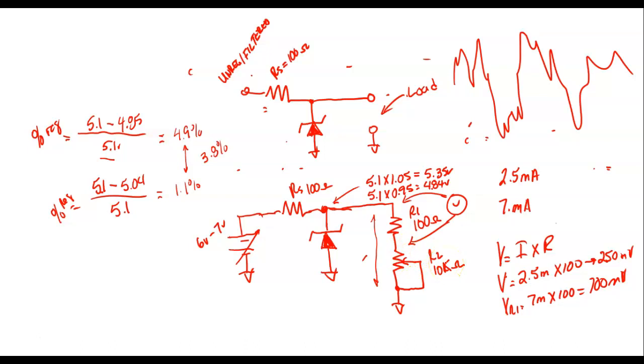So what we did here is we used the voltage changer to change the input voltage, and we went over to the side and used the rheostat to change the R2 current and the resistance from 250 to 700. Once we make that change, we go to minimum, then go to the center and check to see if it's within tolerance. Just say within tolerance.